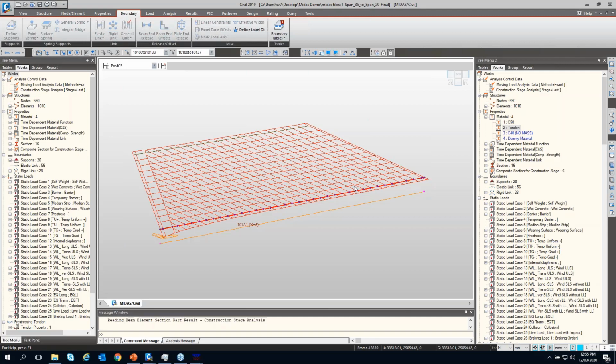If it is continuous, it tries to deform the whole girder in the shape of the applied pre-stressing loading. But when you have supports on a continuous girder, they're trying to restrain the deformation of the girder, which induces reactions in the supports, and these reactions in turn cause secondary forces on the girders. I hope I'm making it clear, but you can still come back to me after the session if you are still not clear with the pre-stress secondary effects.